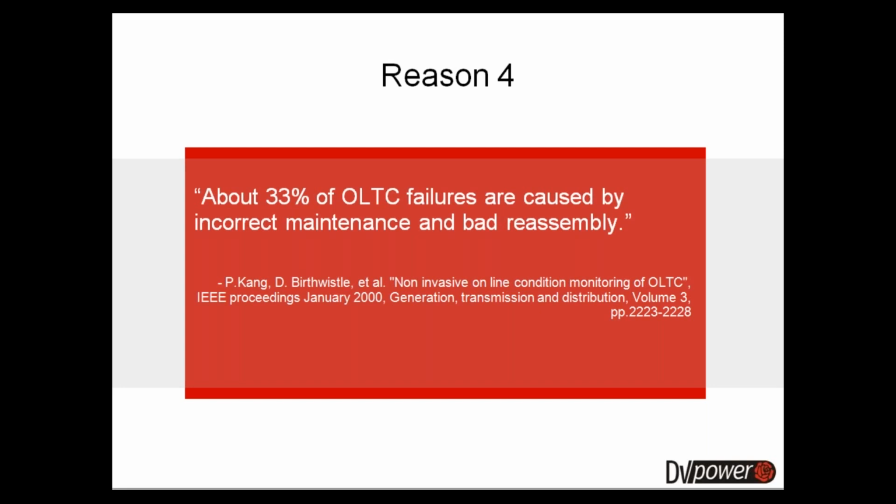And finally, when you are taking the transformer apart, disassembling the tap changer and cleaning and doing various maintenance works, sometimes it is very easy to make a mistake when you are putting the tap changer back together. For this reason, it is recommended that after you finish maintenance and reassembly, the tap changer is inspected using a non-intrusive method such as DVTest in order to make sure that the tap changer can be safely put back into service.